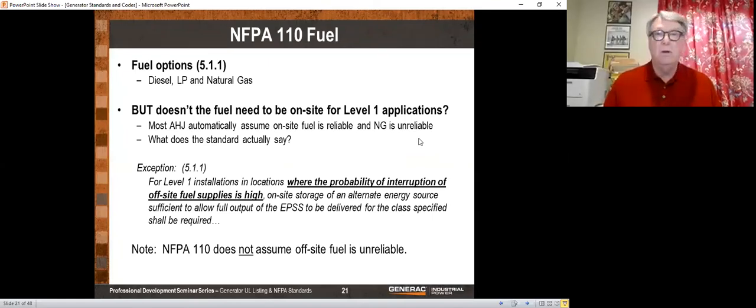We're going to want some very, very large diesel tanks there. But my opinion is that you're better off with a natural gas generator in things like hotels, because diesel generators are very maintenance intensive, and you have to test the fuel, and the fuel might need replacing. And so in general, a natural gas generator is more likely to be operable in a power outage or in a disaster. And a lot of people say, well, in an earthquake, that may not be true, but actually we find that it is true. In areas where there are earthquakes, the government in their studies have found that a natural gas generator is more likely to be operable than a diesel generator.